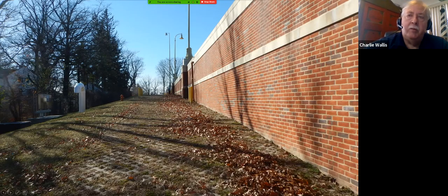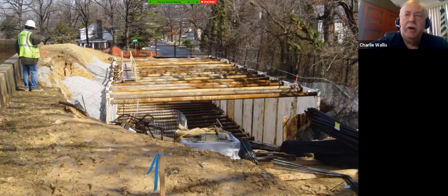Here's a real life example in Maryland where, in this case, it's a reservoir, and there's an underground structure here. But during construction, when this was excavated out, this wall for the reservoir started to move. So additional bracing was required, and additional fill was placed between the forms and the existing dam so that movement was arrested and stopped.